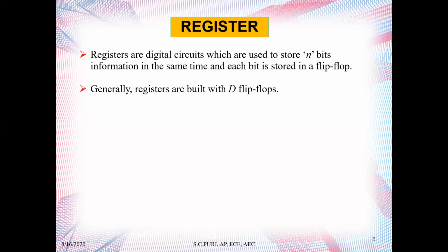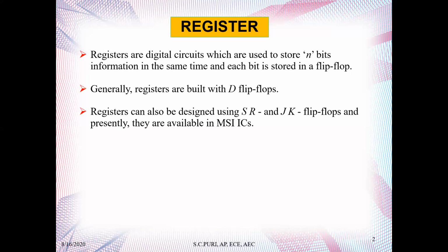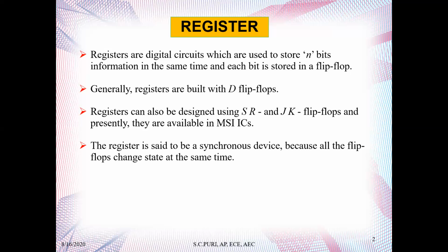However, that doesn't mean that we can't use any other flip-flop. A register can also be designed using SR and JK flip-flops, and presently they are available in MSI ICs, okay? Medium scale integration. The register is said to be a synchronous device because all the flip-flops change state at the same time. Okay, so it is synchronous in nature.